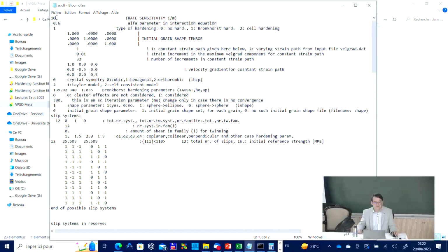If you put here a very low value, like if you put 100, then the code is not sure to run, because the calculation implies a Newton-Raphson iteration process at 2 levels. If the yield function becomes very sharp, because you have such a low value of strain rate sensitivity, it concerns the shape of the yield surface.